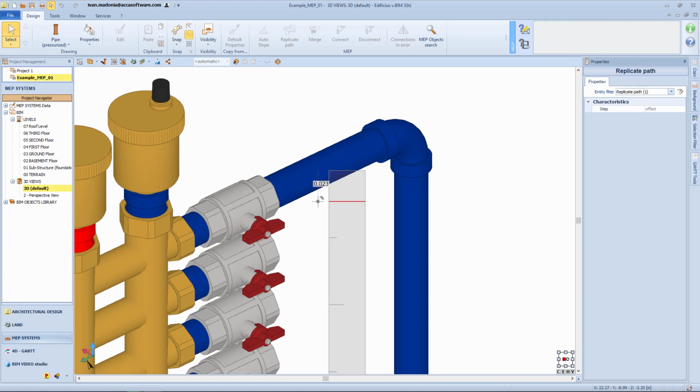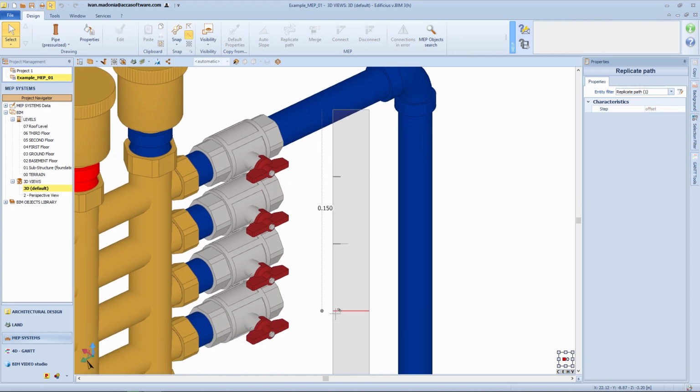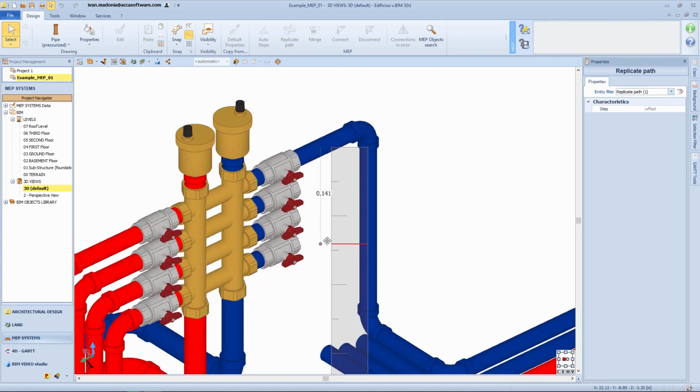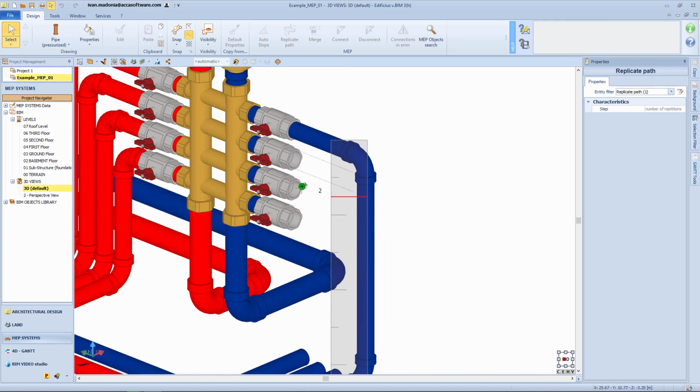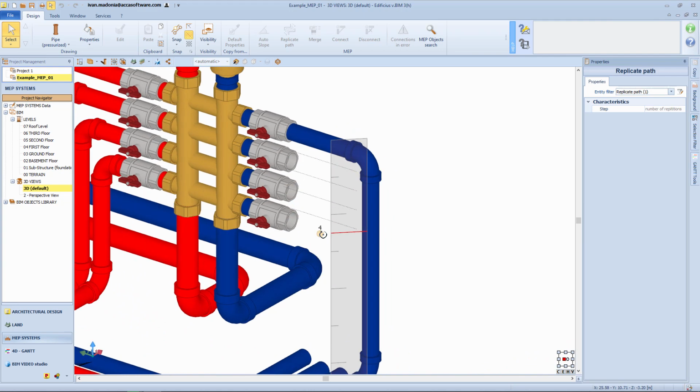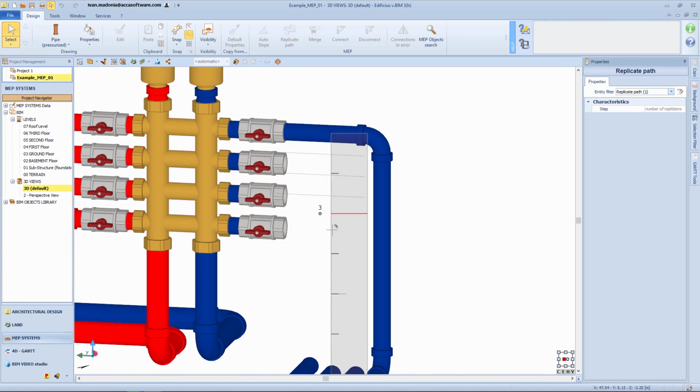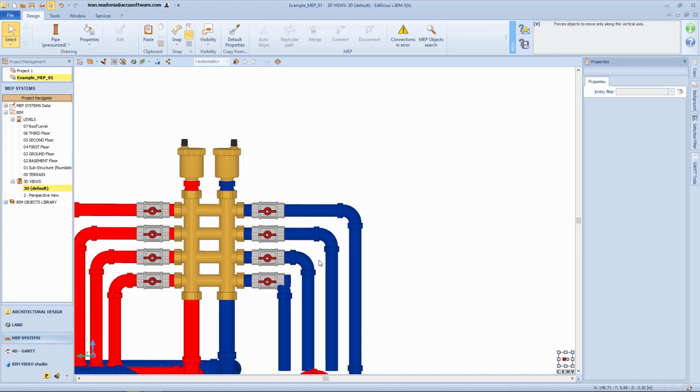After fixing the direction, the protractor disappears in favor of a ruler that allows you to select a distance that will be indicative of the distance between replicas. Then it will specify at what distance from the path already made the first replica will be reproduced and, possibly, the second from the before, and so on. Once this choice has also been made, the ruler will continue to be displayed, with the functionality of setting, in this case, the number of replicas to be made.